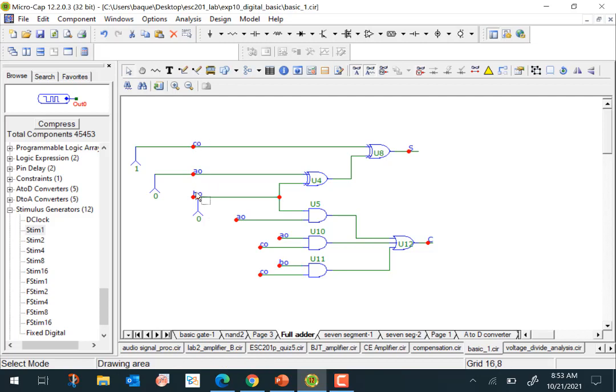So these are the 3 inputs that are there. And connecting wires and all that will become difficult, so it's best to again define a label for each one of these wires. So for example, I've called it C0, A0, and B0. And then when you go to any of these other inputs and you call it A0, it will automatically connect it to this particular one here. So that makes a diagram neat. Otherwise, we'll have a lot of wires crossing each other, and it may become difficult to make the circuit here.